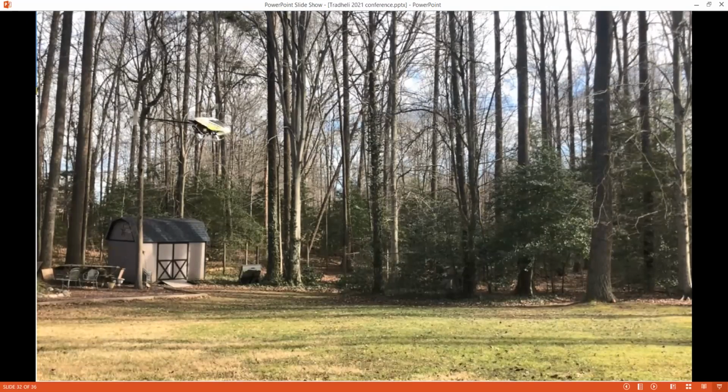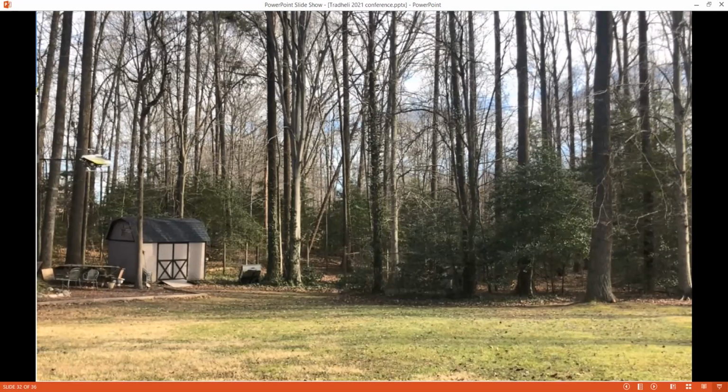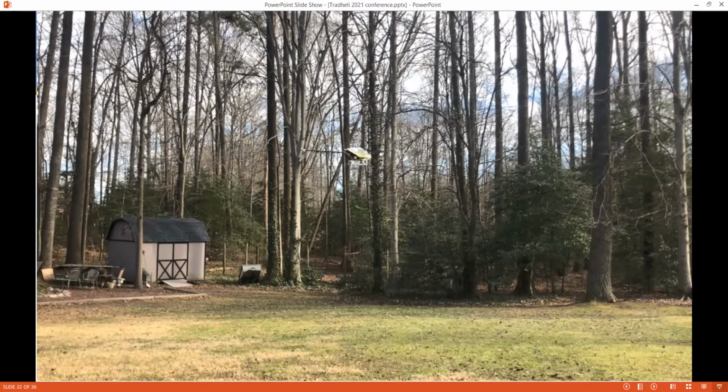I got a quick question, Bill. I take it you're not actually changing any of the gains here, or are you keeping your P gain the same and just oscillating at different frequencies to characterize it? Yeah, great question. So this first sequence of frequencies is essentially doing a spot frequency sweep, right? It's keeping the angle P the same for this whole sweeping of the frequencies. And then it finds the frequency where it sees the maximum response, goes back to that one, and then starts increasing the angle P gain for that response.